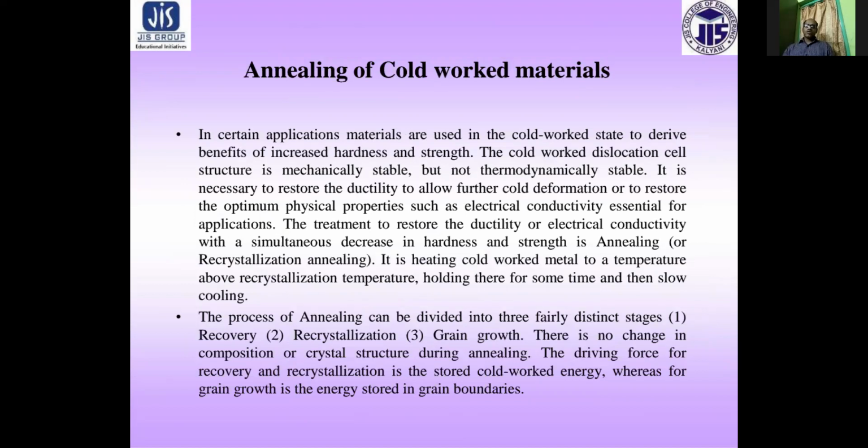Annealing of cold work material. In certain applications, materials are used in the cold work state to derive the benefits of increased hardness and strength. The cold work dislocation cell structure is mechanically stable but not thermodynamically stable.